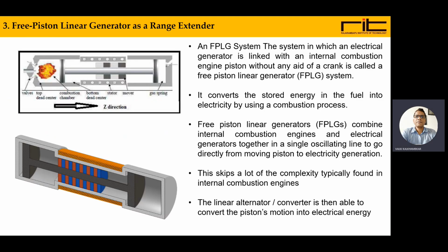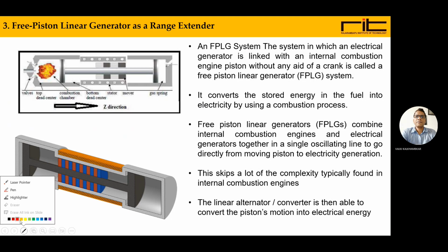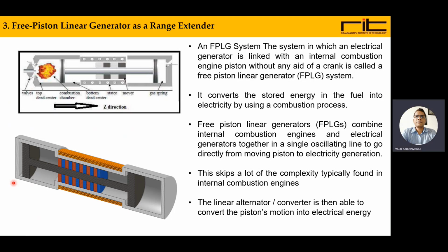The free piston linear generator as a range extender. As the title suggests, it is IC engine based, but having the linear movement of the piston, and it is coupled with the generator. So a free piston linear generator system is the system where an electrical generator is linked with an internal combustion engine piston without any crank.